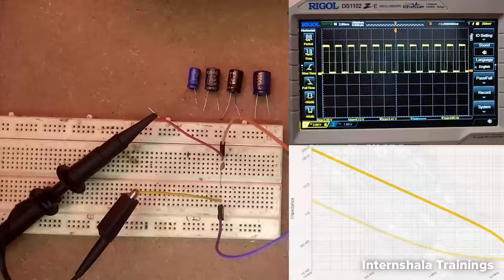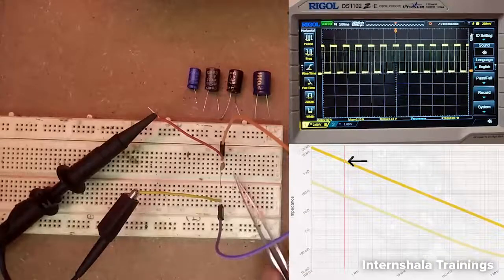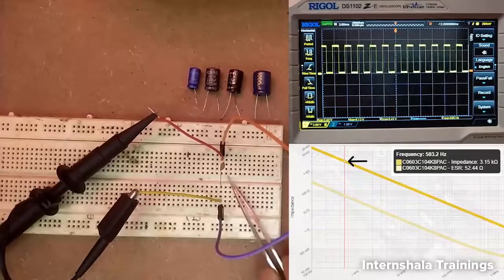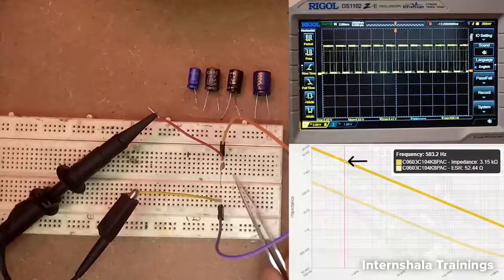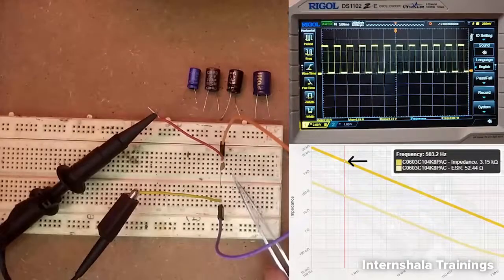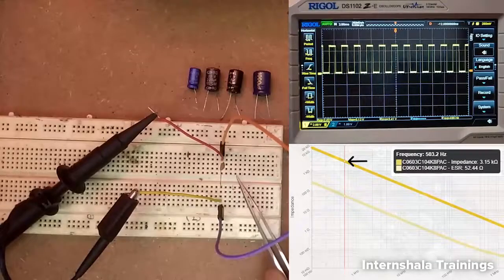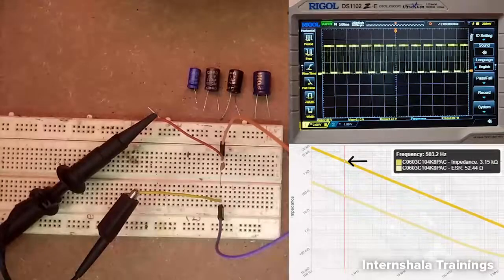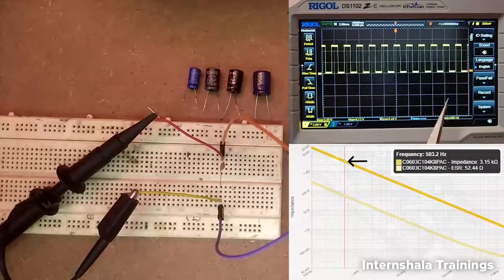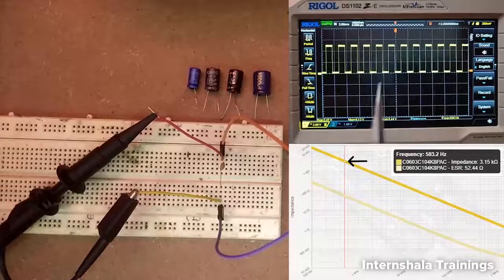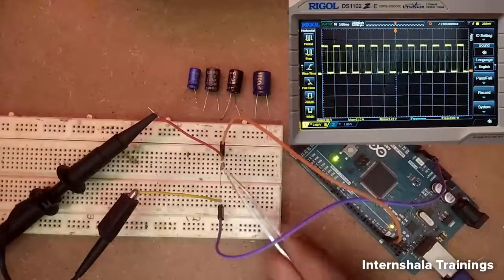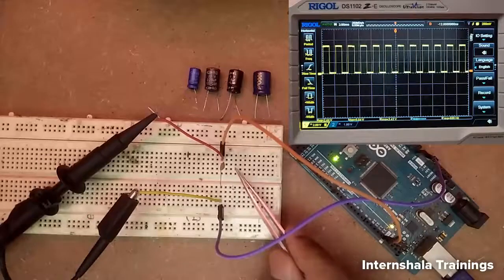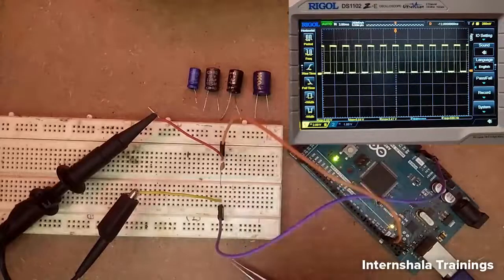Even higher impedance. So I will put the image of the impedance versus frequency plot for this particular capacitor, and you will see in that plot what impedance this capacitor is providing at 500 Hz. I think it's providing an impedance of around 1 or 1.5 kilo ohms. That's the reason we are still getting that frequency on the output side, which you can see on the DSO. So this tells us that this capacitor is not good at all at filtering this 500 hertz frequency. So I will remove this capacitor now.